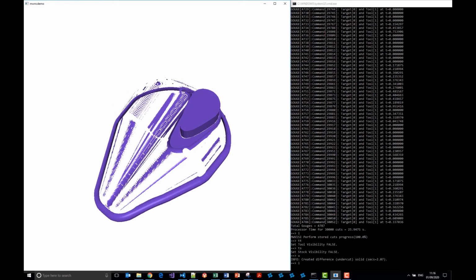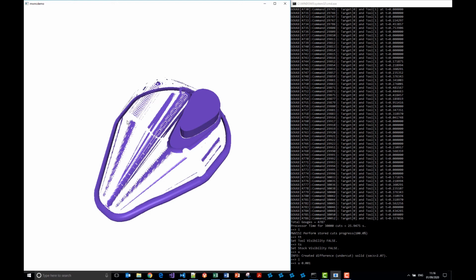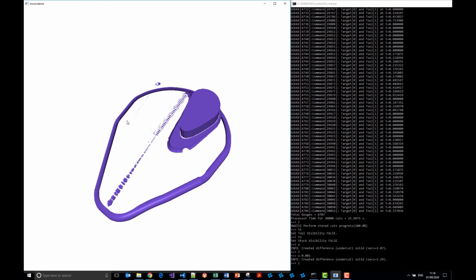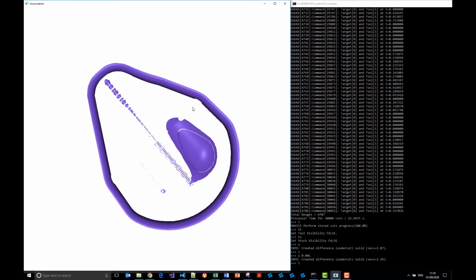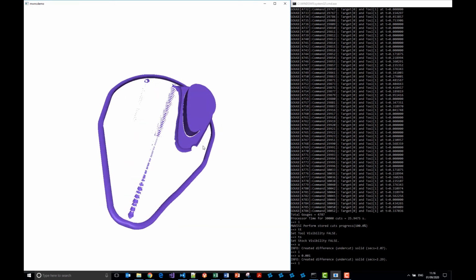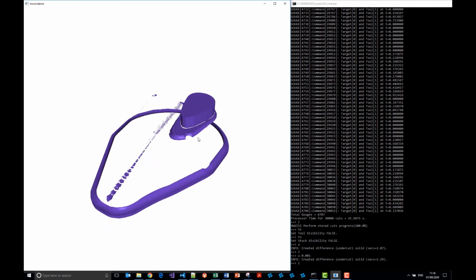And that's where Polygonica's offsetting comes in. So if I double click again, this time MachineWorks will call the Polygonica libraries to offset the design part outwards by a small amount, in this case 1/1000th of an inch. And then when MachineWorks redoes the Boolean subtraction, we'll see that a lot of noise has been filtered out, and we're left with the thicker regions of solid material. And there you have a much nicer, cleaner result suitable for analysis.